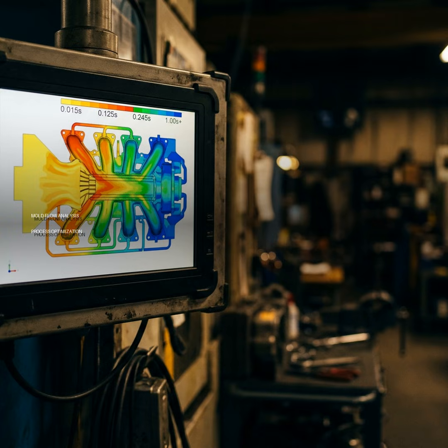Okay, so you've got the gate set. What's the output data that really tells you if it's going to work? The fill time results are critical. They show the melt flow front expansion. You want a balanced filling process where the melt reaches all parts of the cavity at roughly the same time. This highlights short shots where material doesn't fill an area or hesitations where flow might interrupt. It can also point to overpacking if too much melt is forced into a path.